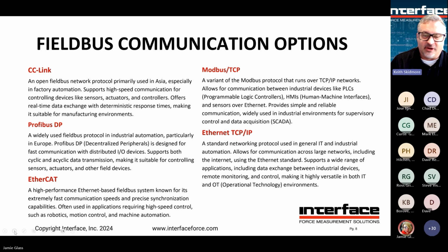Again, some of them may be used by certain manufacturers. Allen-Bradley may commonly use EtherNet/IP, or Siemens may use a different protocol. Again, it's not necessarily one is right or wrong. A lot of times the network exists, and the answer is for your sensors, you just want to connect them into an existing network. Of course, if you're starting from scratch, usually you don't start with a sensor and build a network around the sensor's protocol. You would decide on a protocol and then pick the appropriate sensor to interact with your network choice.